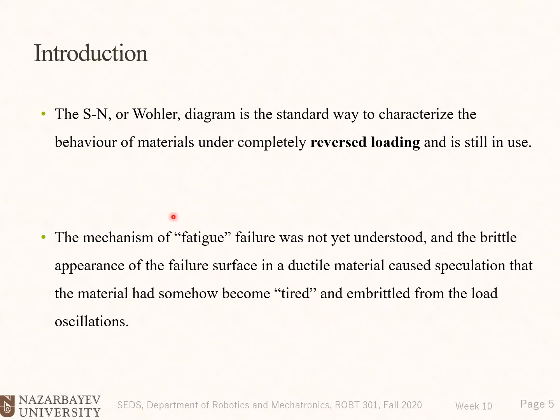The name comes from this historical observation, but of course, the real mechanism of failure is not about being tired. Still, we use the term fatigue failure. When we say fatigue failure, we mean dynamic failure, or failure under dynamic loads, and of course it has its own mechanism, different than static failures.